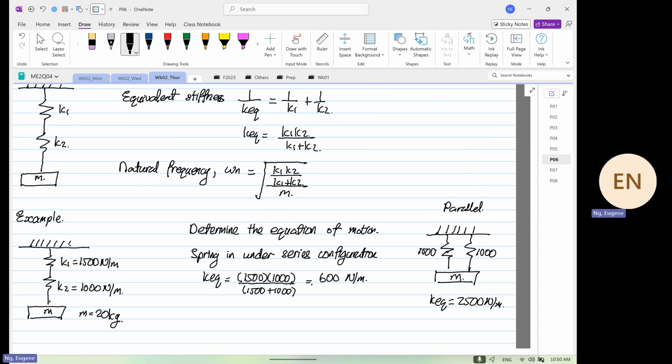If you have two springs, if you want to reduce the stiffness of your system, what will you do? Put them in series, right? Let's say you are in a certain place in Timbuktu where you don't have Home Depot, but you have two springs, you want to reduce the stiffness, what do you do? Put them in series. And if you want them to be stiffer, put them in parallel. I'm trying to figure out, do I ever see a spring configuration in series? I've not. So this is just for making your life difficult. Are we clear?